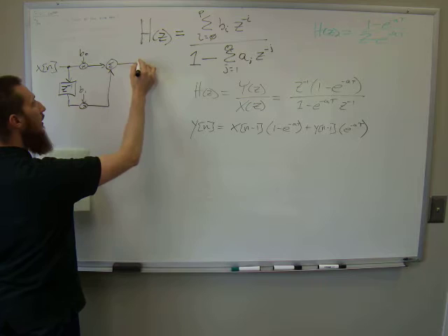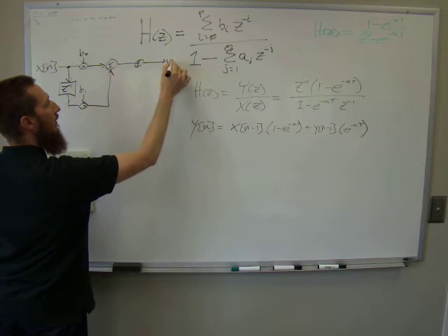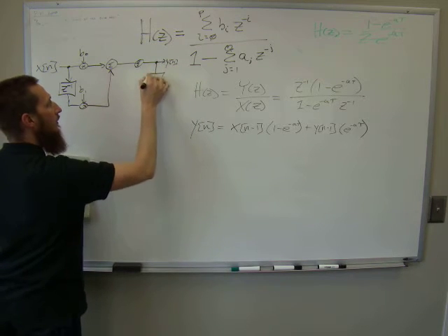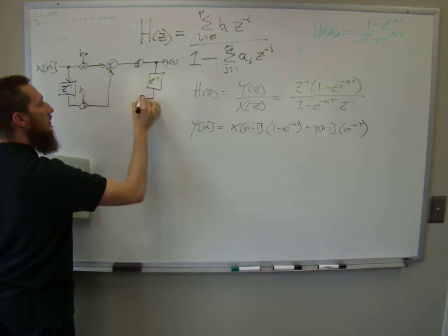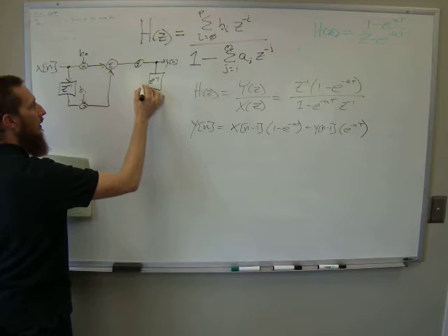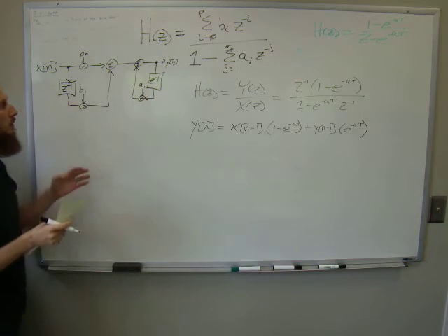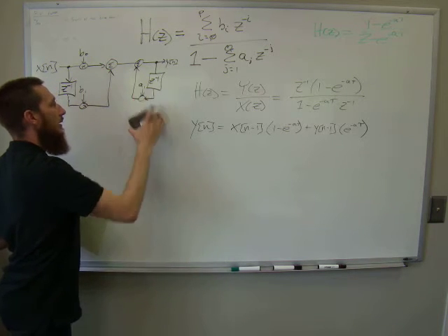And then on the other side, this is going to come out, and this is y of n. And y of n is tapped off and is delayed, z to the minus 1. And this comes through a multiplier. This is multiplied with a of 1, and then fed back into the summation block. So this is a multiply block down here at the bottom.